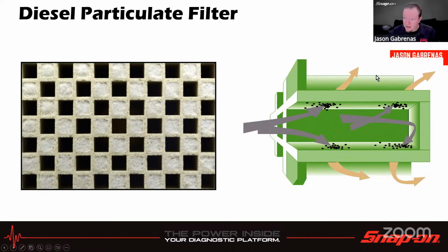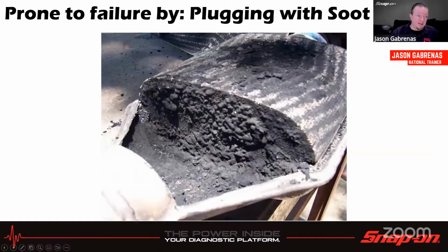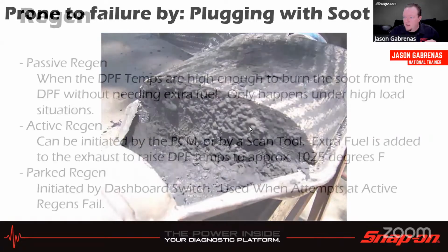Now, over time, it should regen, depending on what conditions are. It should. But sometimes customers may ignore it. Vehicle owners may ignore it. And then it could get to the point where it's like this. And then at that point, you're not going to be able to save it. And you're pretty much just going to have to replace it at that point. So that is just chock full of soot, just oozing out of it. Really, completely restricted exhaust at that point.